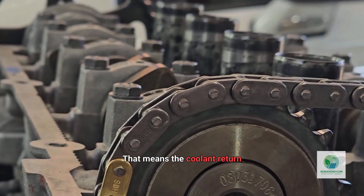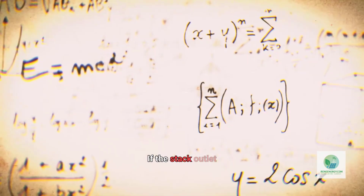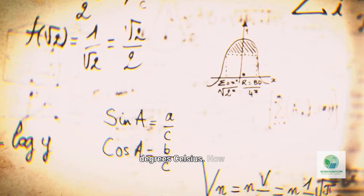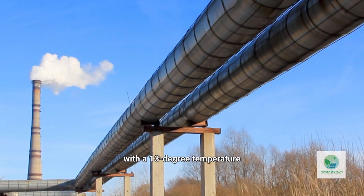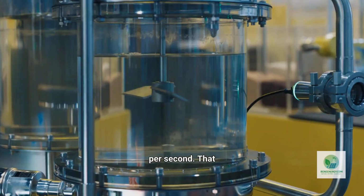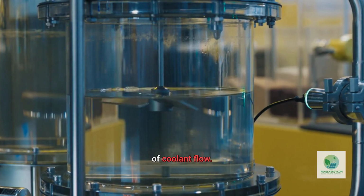That means the coolant return temperature cannot be lower than 62 degrees Celsius. If the stack outlet temperature is 75 degrees Celsius, then the available temperature difference for stack cooling is only 13 degrees Celsius. Now apply the equation. To remove 17.7 megawatts with a 13-degree temperature rise, you need a mass flow rate of 325.7 kilograms per second. That is nearly 19,540 liters per minute of coolant flow.